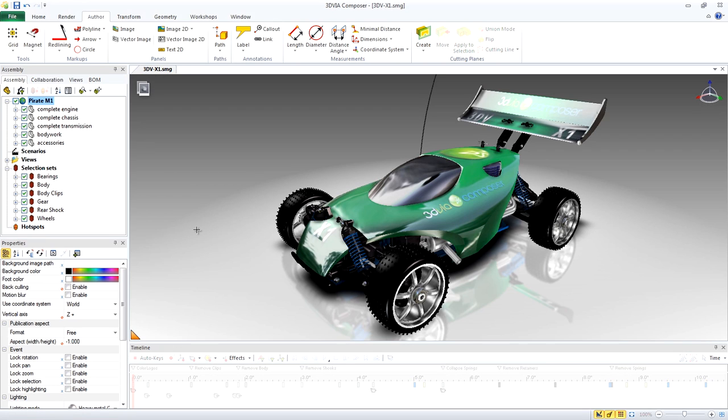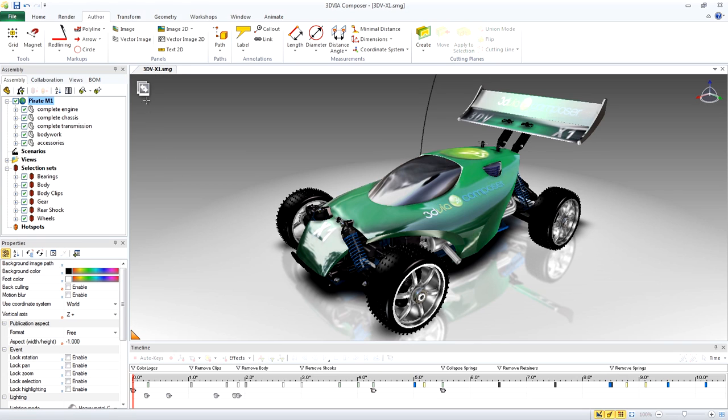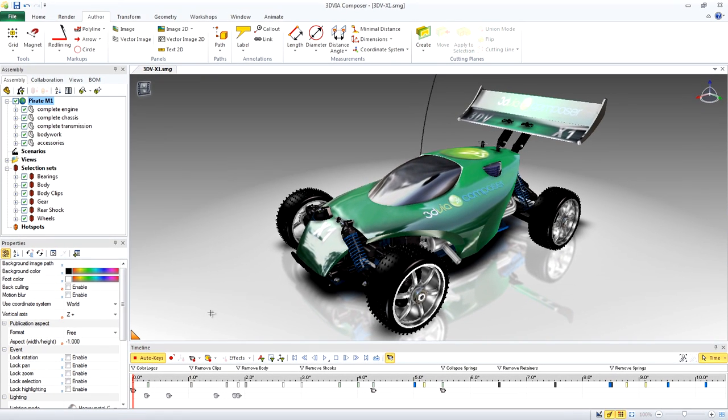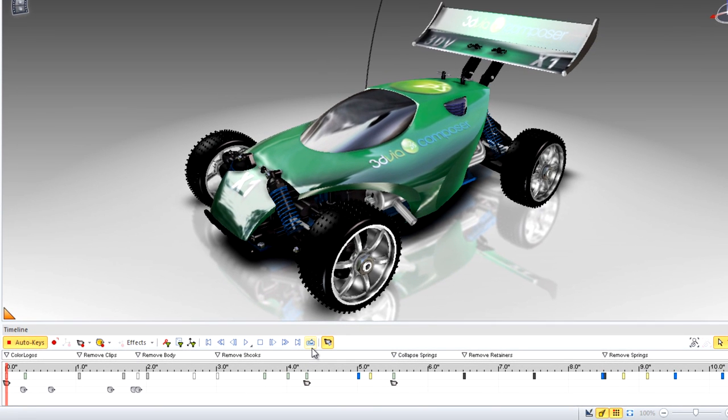Click the icon in the upper left of the viewport. Notice the tools on your timeline pane at the bottom are now active. This is an interactive animation, so we're going to turn off design mode to show the interaction. In your timeline toolbar, make sure Loop Play is turned off so the video only plays once, and then click Play.